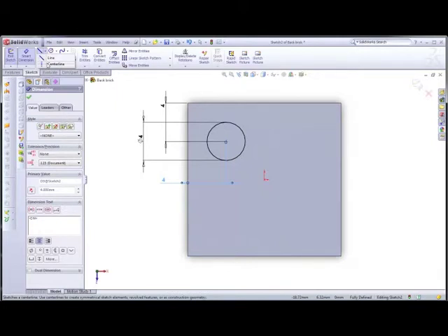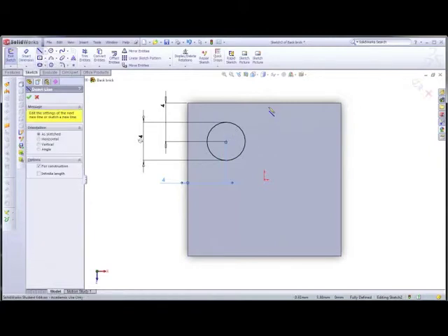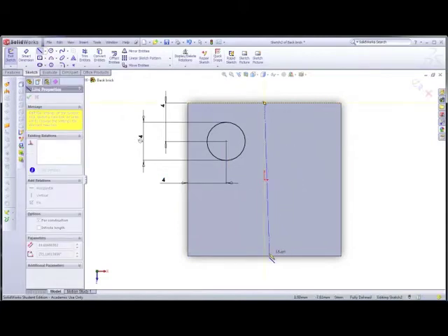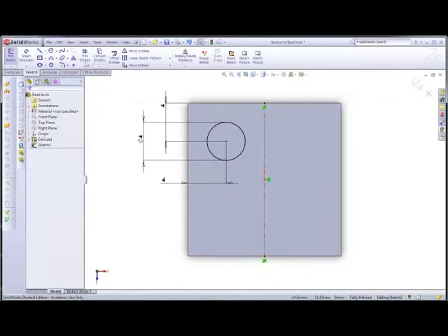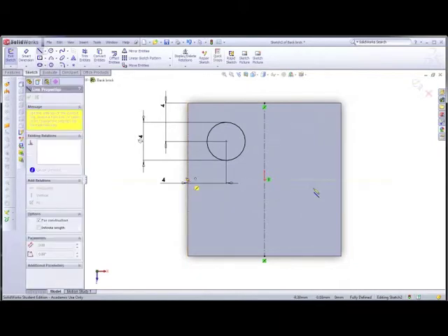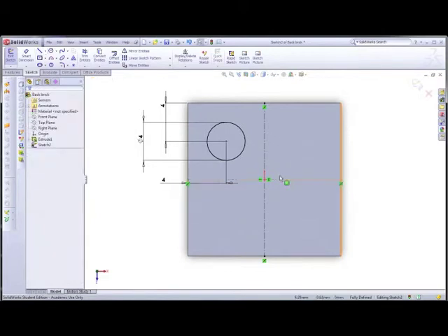So we use the center lines basically as our lines of symmetry, as opposed to a line tool. Because if we use the line tool, then it wouldn't allow us to extrude up, because the software would get confused. So instead we use a center line for any lines of symmetry, and this therefore will not interfere with the extrude. Okay, so I want to add 2 center lines just across the center.